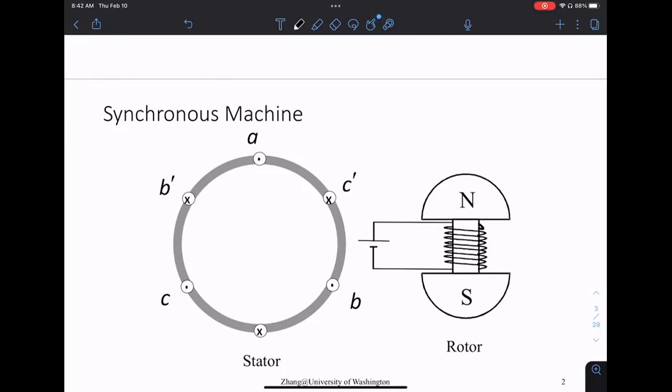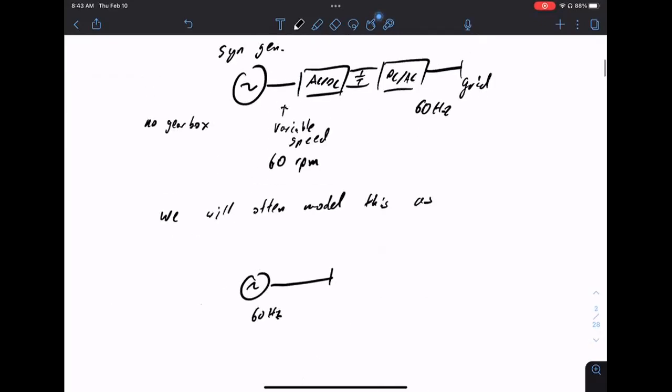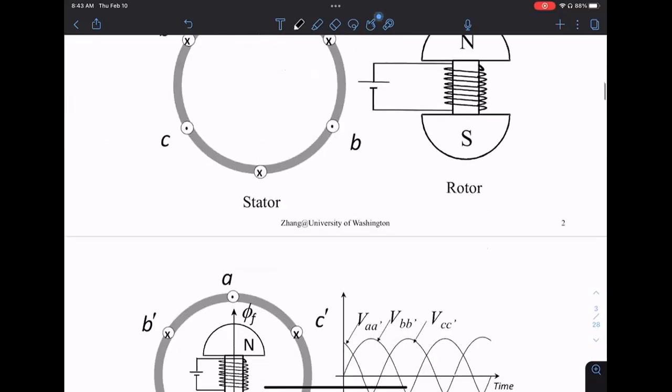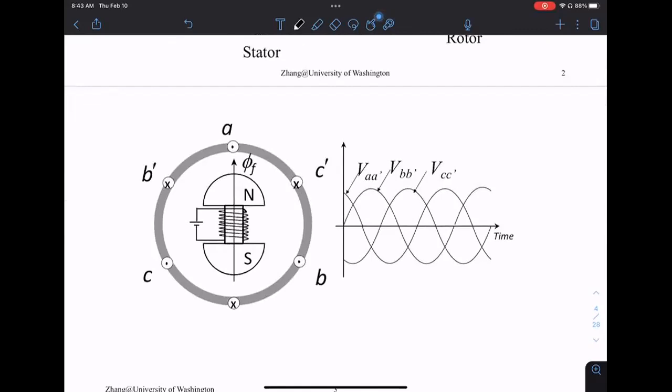So the three-phase nature is actually very important. If you actually look at how you design this electronics, it's very important to have a balanced three phase. So there's a lot of effort spent in these conversion steps to make sure you have a balanced three phase. Here we're going to assume that we always operate at balanced three phase. Okay, so we have some three phase operation, it's always balanced. And the benefit of this is, if you have a balanced three phase, there's no net voltage or net current flow. Everything cancels. Okay.